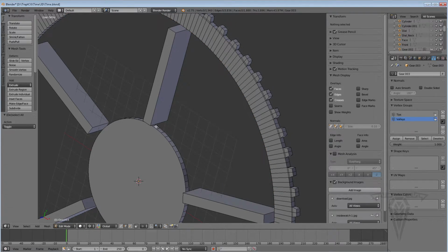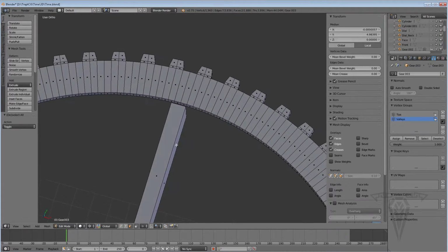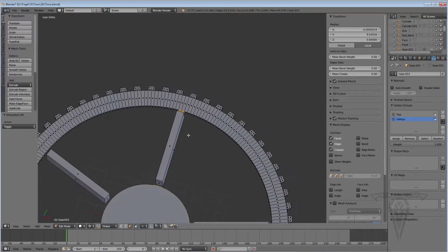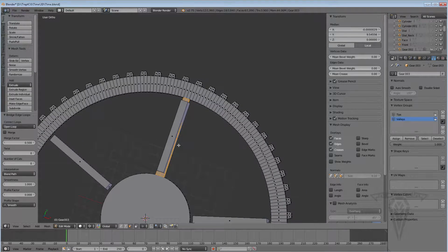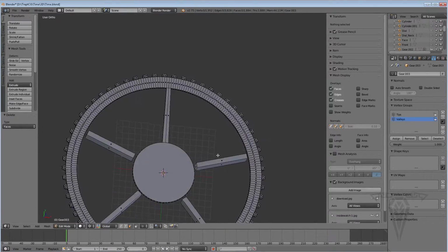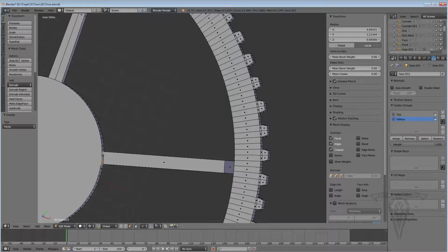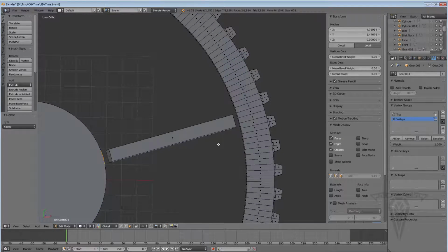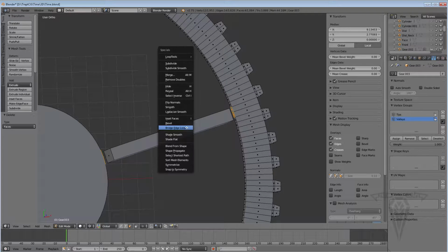I'm going to go A to deselect all. I'm going to go back to Polygon mode. Select this polygon, hold down Shift, that polygon. Come back here at the top, hold down Shift, and go W on the keyboard for bridge. Voila. Now I can deselect all, roll over this object here, hit L and X, and delete faces. So I can repeat this process for each one of these points. So select, select, select, select, and W, bridge.